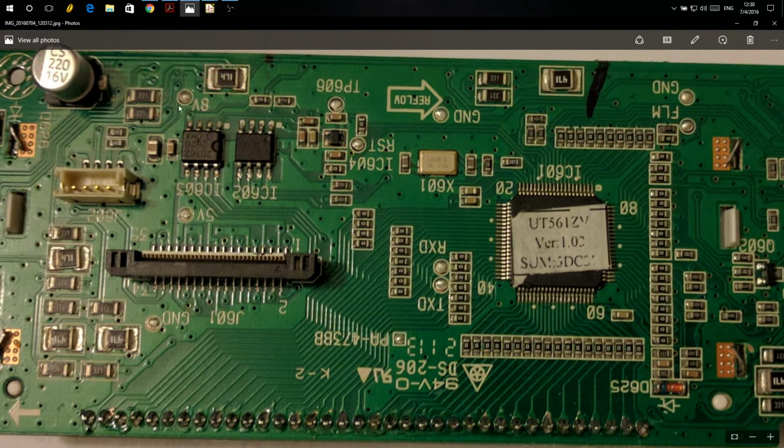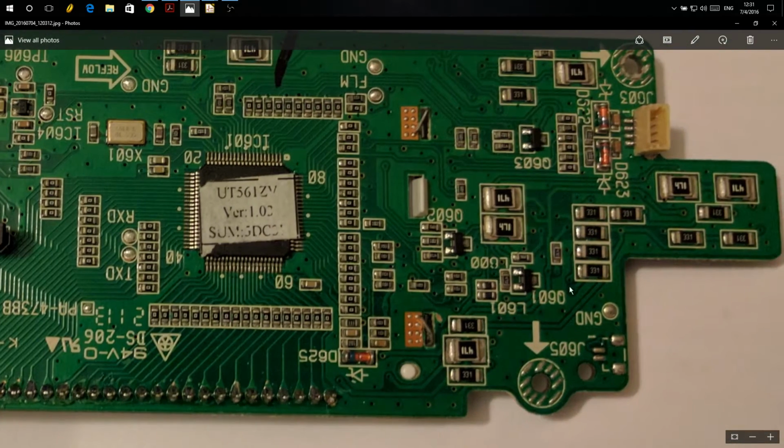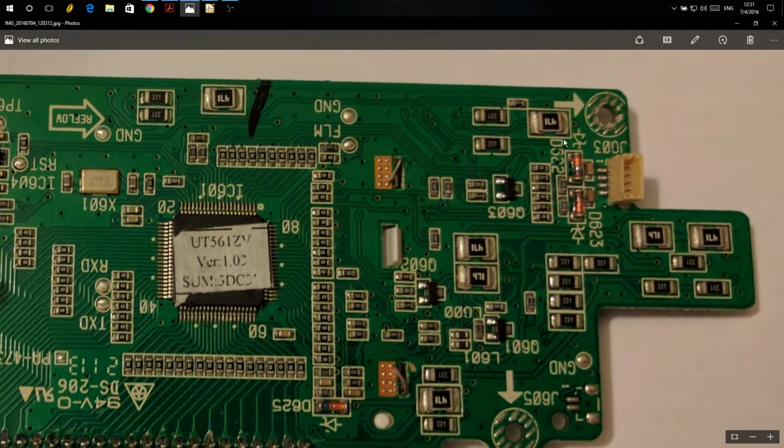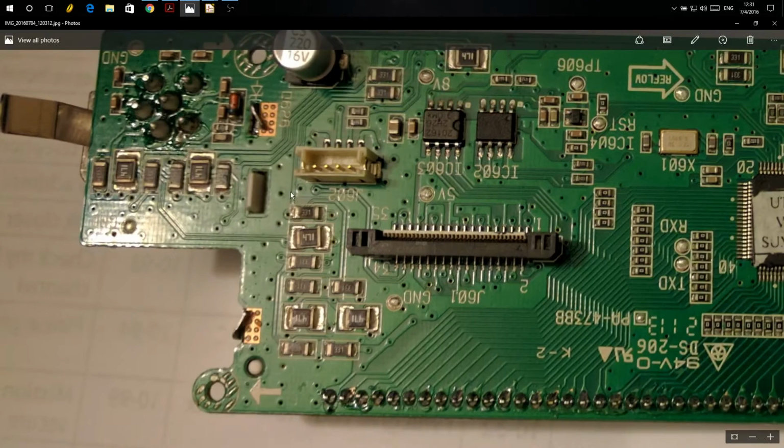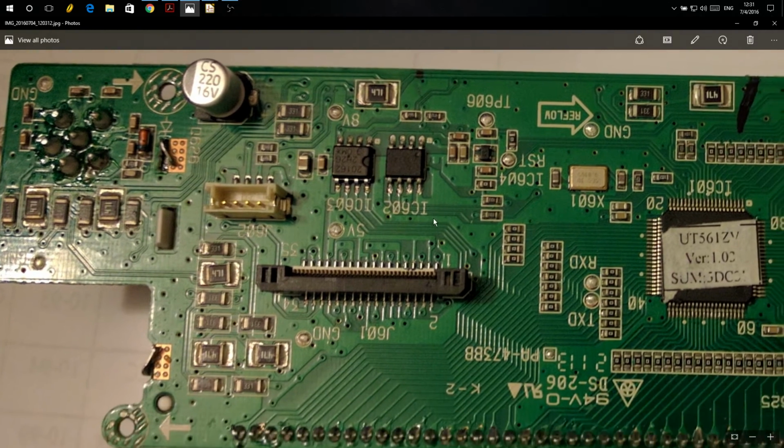We've got, like I said here, our DAC. This is being used for contrast. EEPROM being used for user data. We've got a lot of passives and things like that. We've got some hardware debounce here for the encoder, which is interesting, because this only has debouncing for one pin here, and I believe there's 2 on here, the up and down, and we only have one debounce, so that's kind of strange.